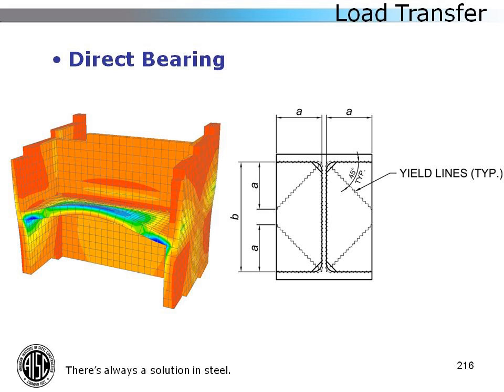And yield line theory is sort of like steel voodoo. You sort of draw some lines out and you can come up with a capacity equation for a connection design like this. It's actually behind a good number of the equations in Chapter J of the specification. So I highly recommend taking a look at that method. So we provide those equations within the design example.